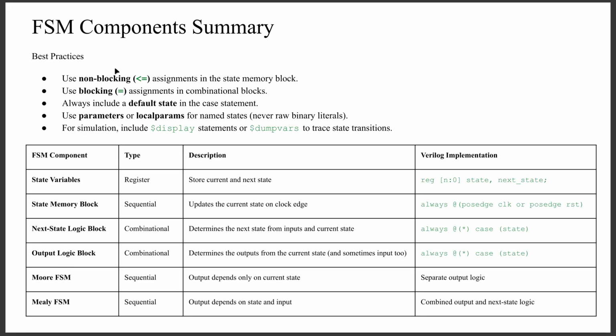So, in summary, use non-blocking statements in the state memory block. Use blocking assignments in combinational blocks, and always include a default state in the case statement. Use parameters or local parameters for naming states. For simulation, include display statements or dump files to trace state transitions.